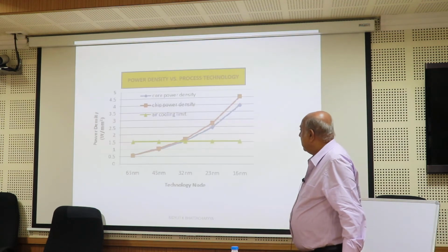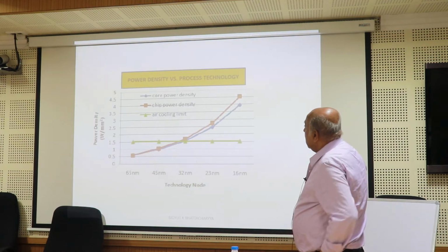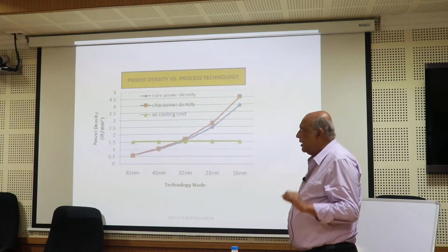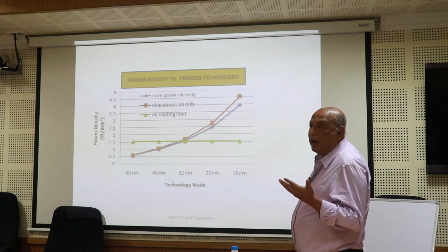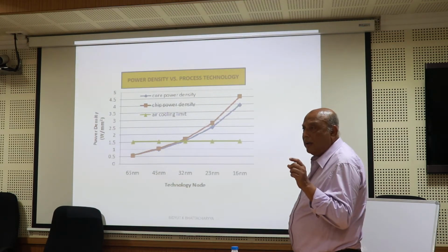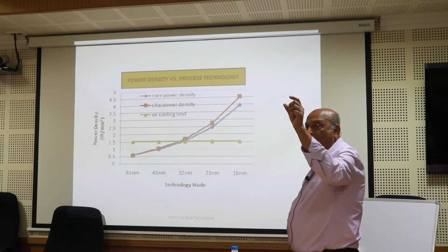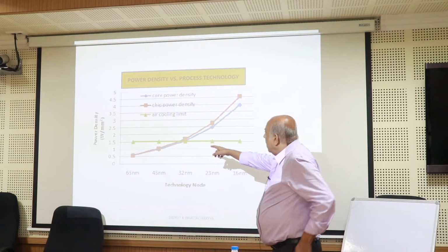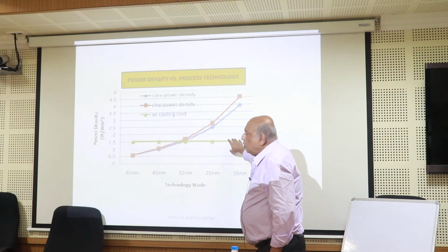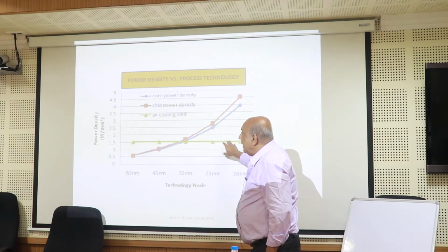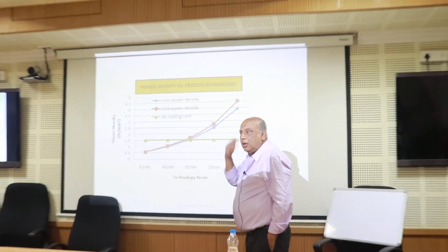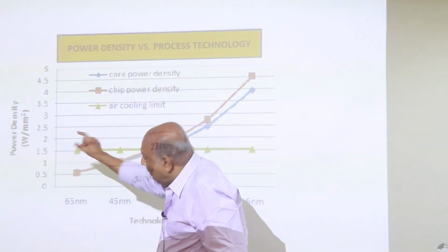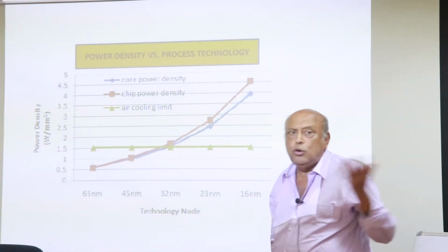Next file. Now this is something, power versus density curve. We'll talk about the meaning of it. Our power and the area is about 1.7 watt per millimeter square, because it's 300 watt and the area is 0.3 by 0.3. So use a plot of, if you air cool with high speed air, you can only cool up to 1.5 watt per millimeter square. You cannot cool below that.